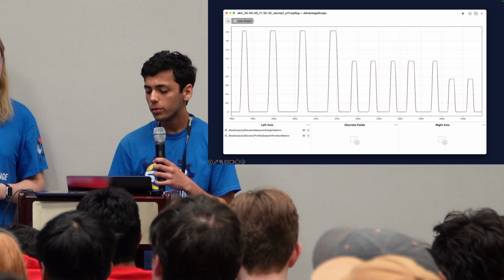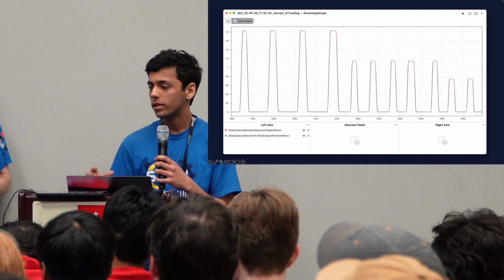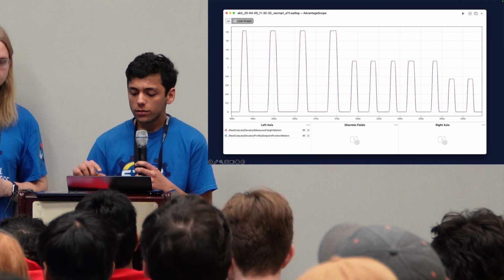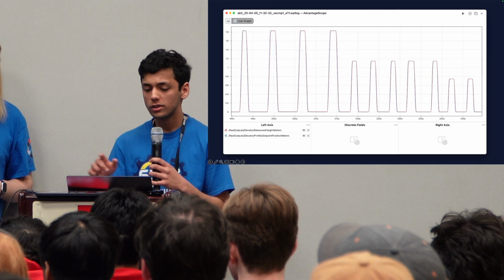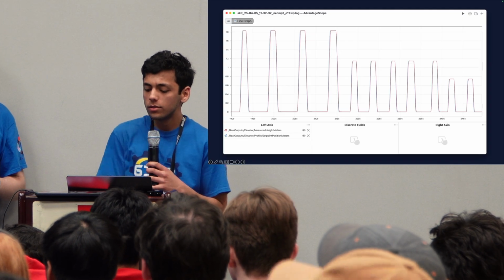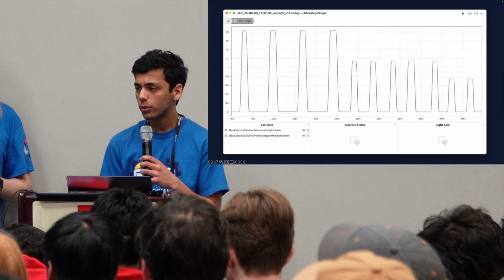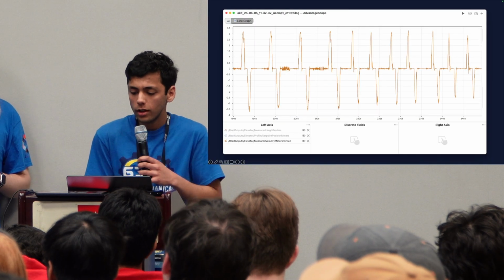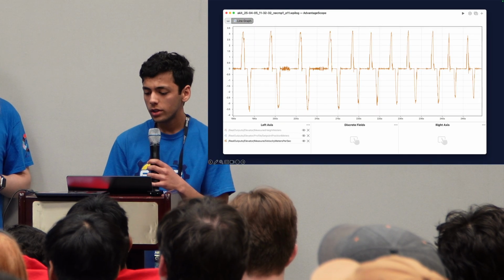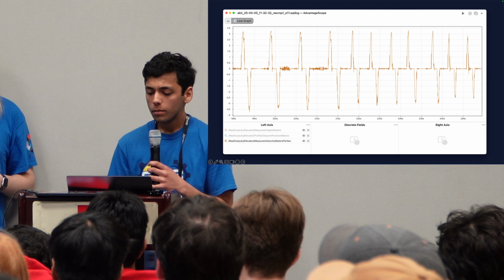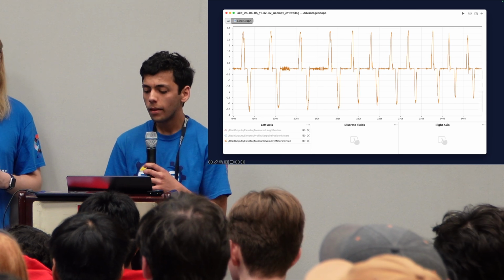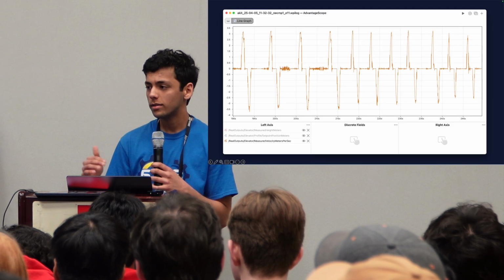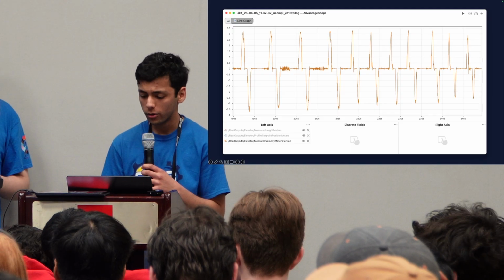And you can see that tracking seems to be working pretty well, but that's only part of what we would be realistically outputting in a real match. Another thing is that each of these intermediate set points has both a position and a velocity. So this is the position. The other thing that we could track is the velocity, because we want to be sure that the feed forward that's running on the elevator is working properly. So we can switch to a graph of measured elevator velocity here. And we can see the velocity is changing when we're driving to the set point. But there's an important piece of the puzzle that's missing, which is the set point for the velocities. So we saw earlier that we are logging the set point for the position, but unfortunately, at the time of this event, we weren't actually logging the velocity set point.